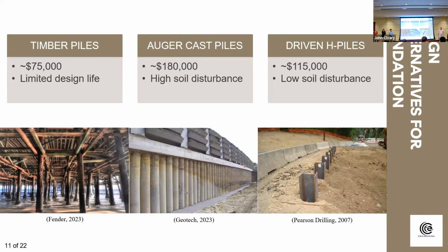So what about corrosion, since this is going to be next to water? Are y'all worried about that with your piles? We considered a smaller pile size, and we took into account the sunlight on account of the corrosion. The corrosion levels for Missouri were counted into the pile sizes. And with this being mostly impermeable clay, all of the piles will be behind impermeable clay. Also on the back sides of the bridge, to protect our pile caps and our piles that are a part of that sandy clay fill, we'll have small sheet pile walls protecting them from any water getting to it.